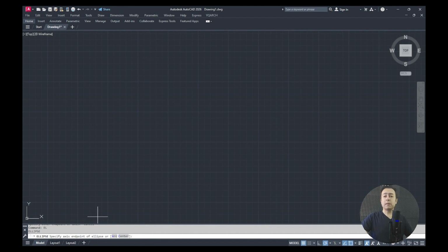When you enter the ellipse command, the first thing you need to do is specify the diameter of the ellipse. So the first thing it asks you is to specify the first end of the diameter. This is the first end of the diameter, and then it says, okay, now specify the other end. So you stand along this direction and enter the length of the diameter. For example, I enter 500. As you can see, from this starting point to here, its length is 500.